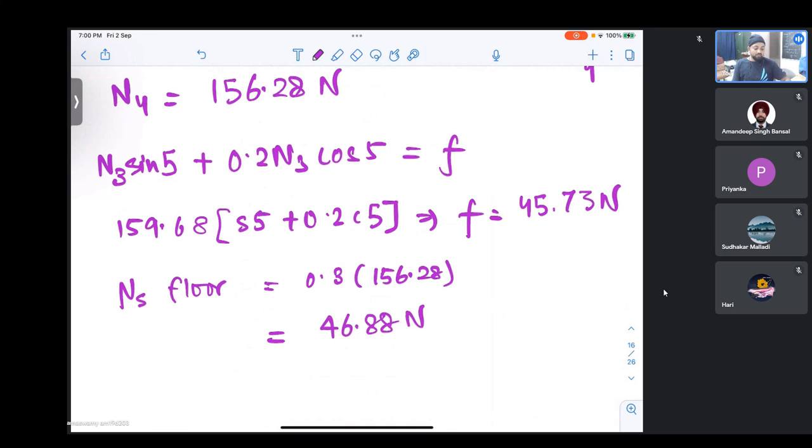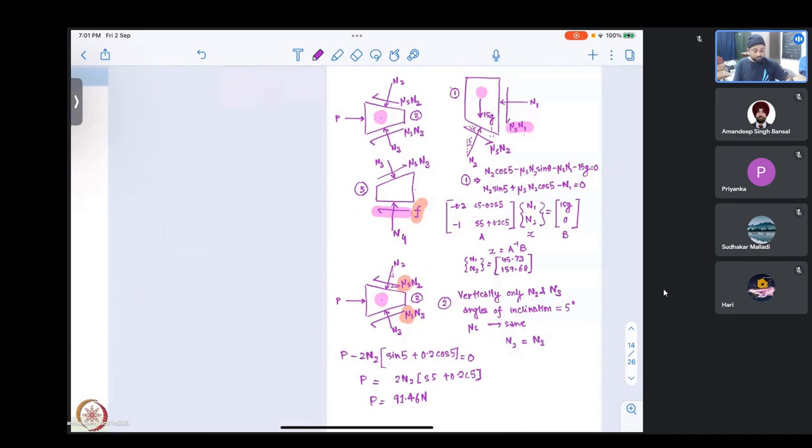So we can see that our mobilized friction in this problem is less than 46, just nearby but still less. So it is possible to have motion like this. That is, it is possible for us to apply force and lift the top block without moving the bottom block. So it comes out that it is mathematically and physically possible.